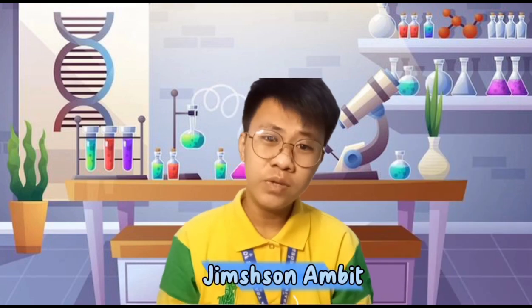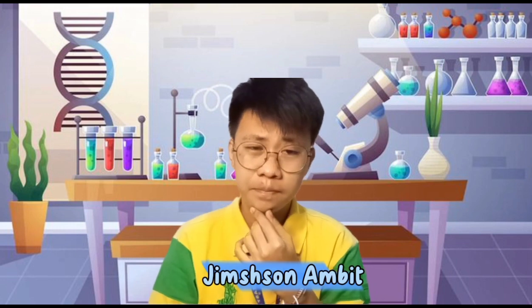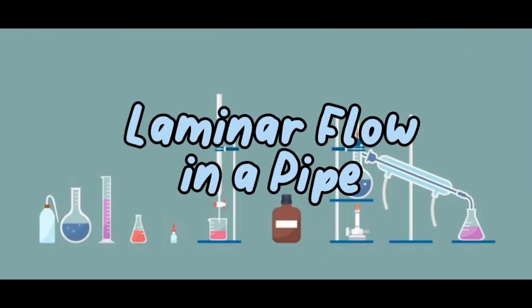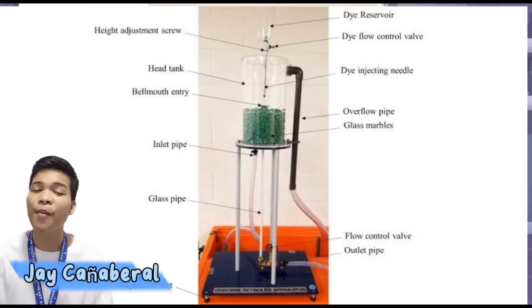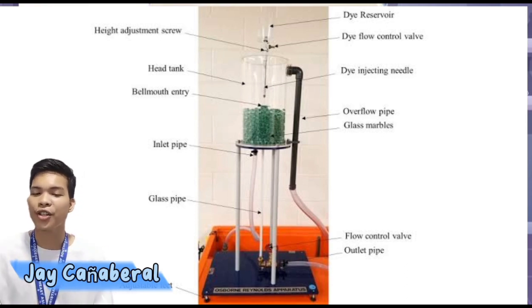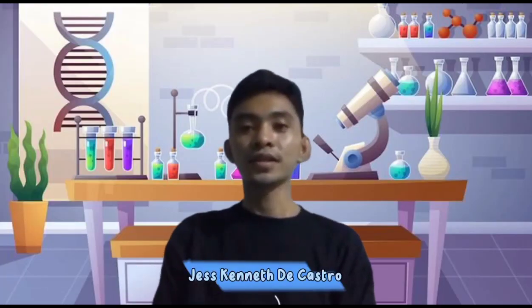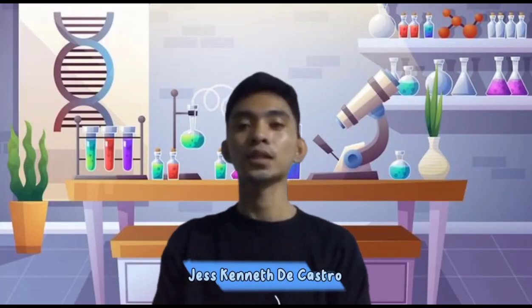So, how do we study the laminar flow in a pipe in a lab? To study a laminar flow in a pipe, we will set up a transparent experimental apparatus. We'll use a transparent pipe with flow rate control, some manometers to measure pressure differences, and a dye to visualize the flow. That sounds interesting. Could you walk us through the experimental procedures?